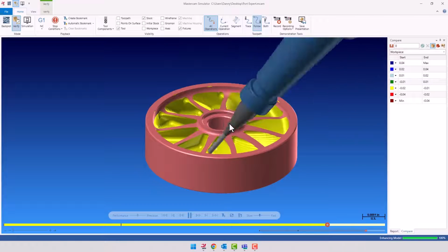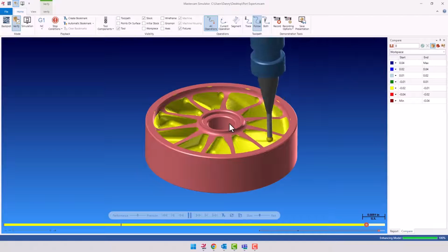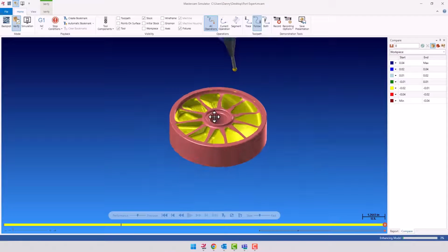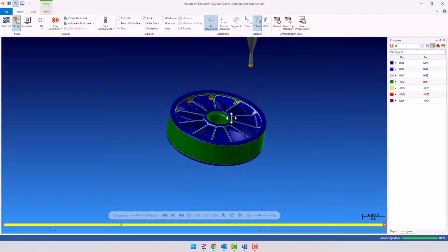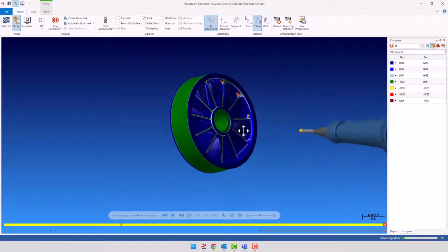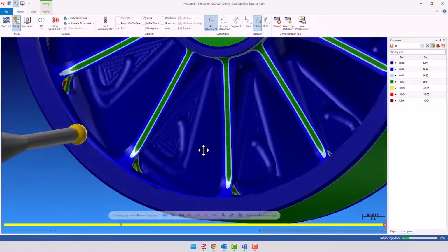I definitely didn't have to create any geometry. Not saying you don't have to. Depends on the model. You might get a model that can be challenging, and we've all run into that, and we still have to create some extra geometry. But when it comes to the actual toolpath, it should be okay. I think I may have bumped into this, but stock is not exactly correct there. My stock's kind of high, but the toolpath itself looks nice and clean right there.